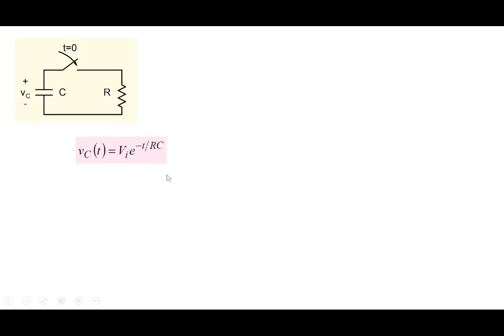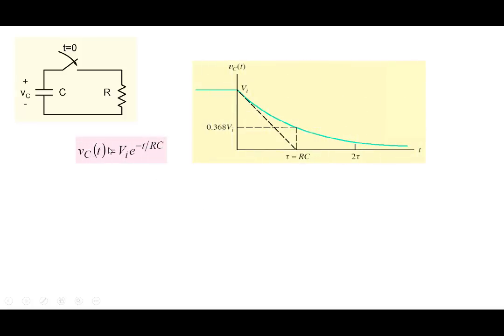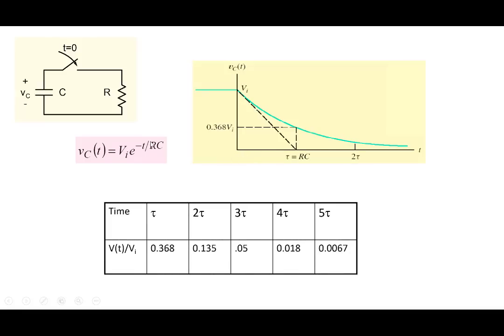Okay, so we have this expression, we can plot it out. And so it starts off, of course, at t equal to 0, the value is Vi, and before that we are saying the value is Vi here. And then this is the exponential discharge here. And most of you are familiar with this particular process. So this term is important. This RC is what we call the time constant. So it is Vi e to the power minus t by tau. And tau is what we call the time constant of the circuit. So in this case, it's simply R into C.